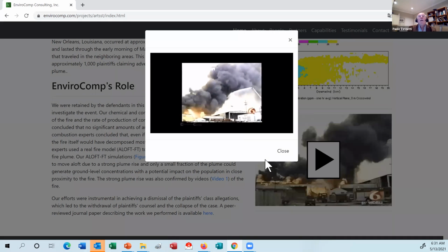But again, that is a mistake, because you only see the plume going up. But actually, if you go downwind the plume at ground level, you will smell a lot of chemicals. So in terms of the color of the plume, the black color, it looks like it's going up with a plume rise. And yeah, probably 95% of the plume is going up to 500 meters. But there is a fraction of the plume at the borders of the black plume that cools down much quicker. And so not all the plume goes up.